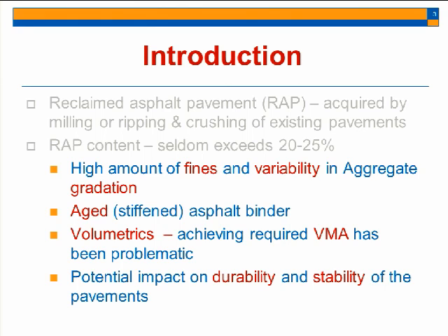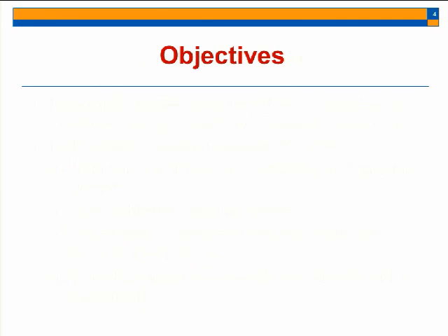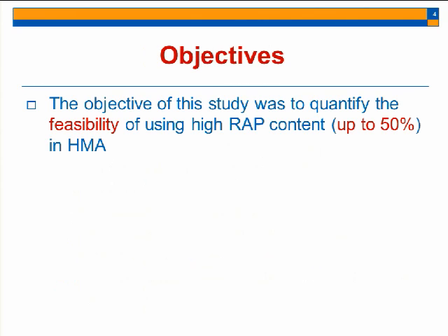We have seen through the literature that people have emphasized the performance properties of these mixtures, but somehow they have overlooked the challenges that volumetrics gave us in designing mixtures with high RAP. And due to these volumetrics and changes in aggregate gradation, there is a potential impact on durability and stability of these mixtures with high RAP. So this brings us to the objectives of the study.